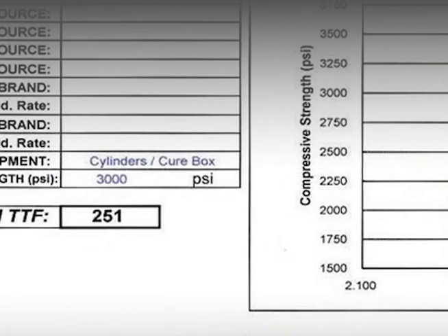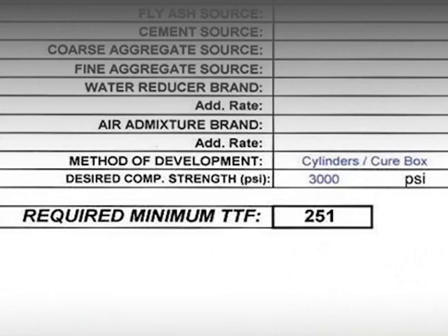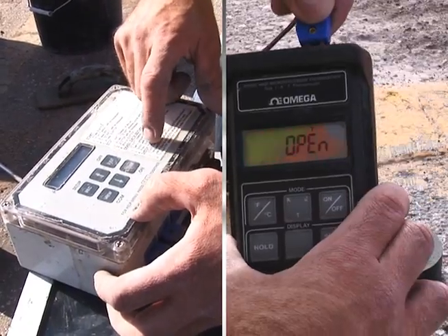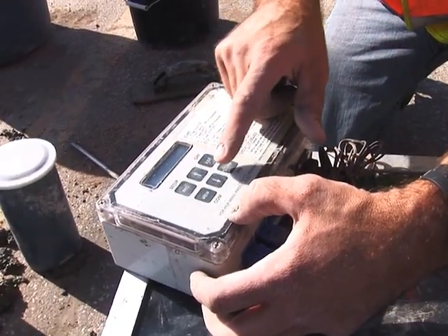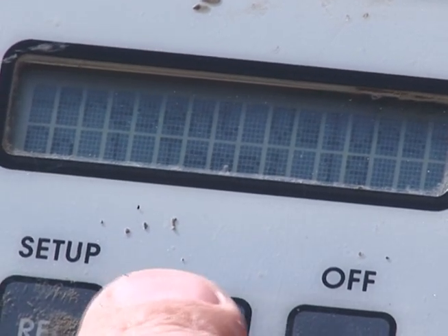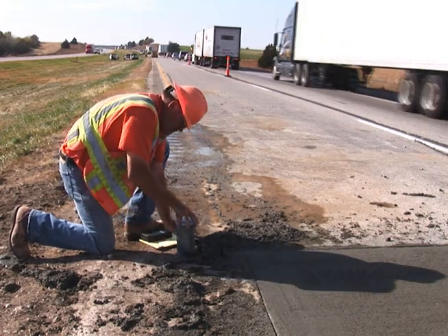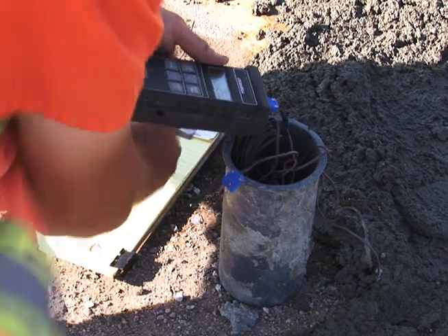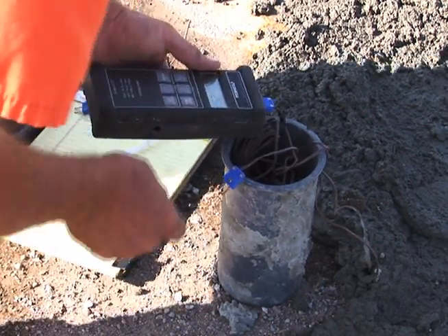The time temperature factor for concrete maturity method can be performed using 2 procedures: a concrete maturity meter or a digital thermometer. When using a concrete maturity meter, the time temperature factor value can be read from the meter in real time. The alternative method is taking the temperature readings using a digital thermometer. These temperature readings shall be taken in degrees Celsius and are used in calculating the time temperature factor value.